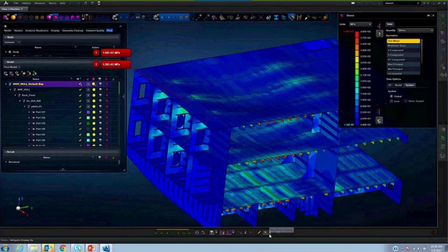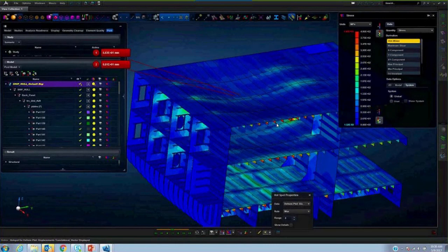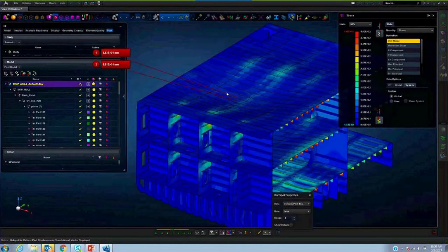And also, can I look at the displacements? If you look here, there is about 55 millimeter displacement in this span. And what it implies is that there is too much sag here, and this is fine. That means as a part-based system, we're able to do all these things. The question is now, can Apex provide us some kind of design alternative? Can I quickly look at what I can do to improve the design? And can we do those kinds of things in Apex?